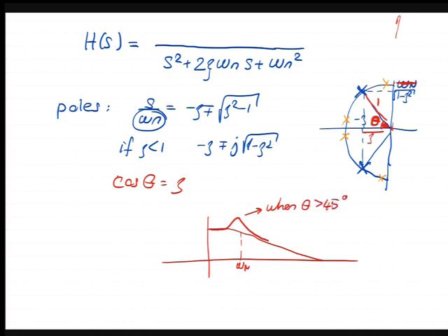So that's the case where the damping is pretty bad. So the poles are closer to the imaginary axis than they are to the real axis, right? And that's when you can show that this h will give you a frequency response that jumps and then goes back. It's no longer monotonically decreasing. What do we call this bump? Resonance, because if you apply its input, sinusoidal input, with a frequency in this range, the system will amplify that. All right?